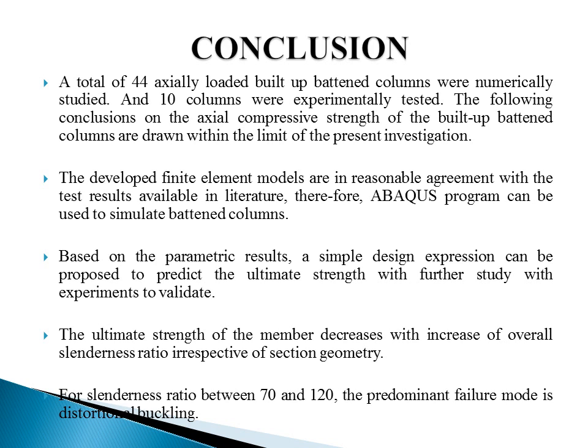Conclusion. Totally 44 axial loaded built-up battened columns were numerically studied and 10 columns were experimentally tested. The following conclusions on the axial compressive strength of the built-up battened columns are drawn within the limit of the present investigation. The finite element models are in reasonable agreement with the test results available in literature. Therefore, the Abaqus program can be used to simulate battened columns.